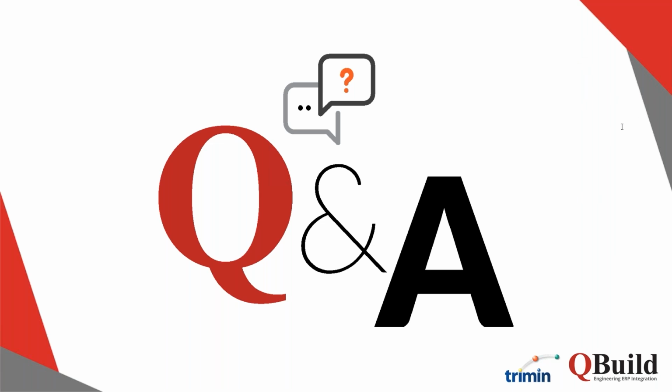Great question here. There's a question about warehouses. So if you're using multiple warehouses in your XA currently, and your assembly is being built in one or more of those warehouses or stored in one or more of those warehouses, will this work with CADLink, or how does that work with CADLink? So CADLink is able to create multiple warehouse records. That's something that you can configure in the settings. If you are pushing to multiple warehouses, you can specify those, or you can have it show up in the interface as a separate column, and you can specify those 2 warehouses you want to push it to. And when you hit save, CADLink will create that warehouse record in warehouse A, for example, and warehouse B.